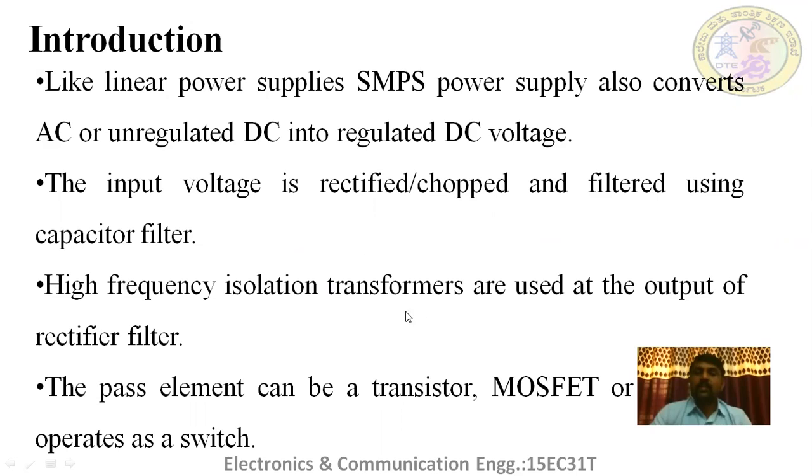The transformers are used as isolators, where the primary winding and the secondary winding have the same number of turns. So therefore, what is present at the primary side is transferred magnetically. So this isolation transformer isolates the primary side of the circuit from the secondary side electrically. There is no physical connection. These transformers are called isolation transformers.